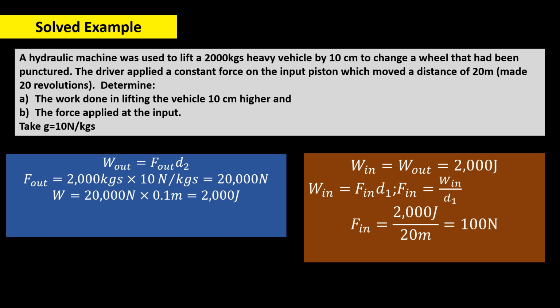I want you to compare the force applied at the input and see how it has been magnified from 100 newtons to 20,000 newtons, and one person has been able to lift a very heavy vehicle, 2,000 kilograms, over 10 centimeters. This is how smart or how efficient Pascal's principle can be.